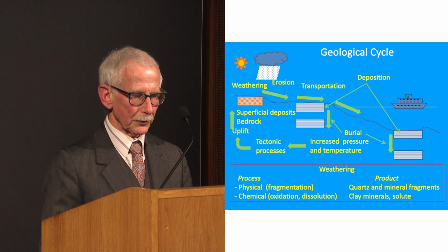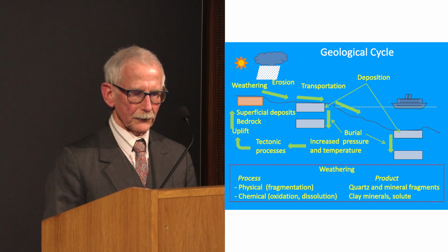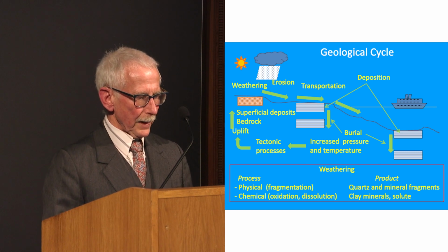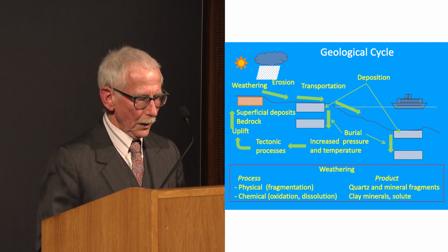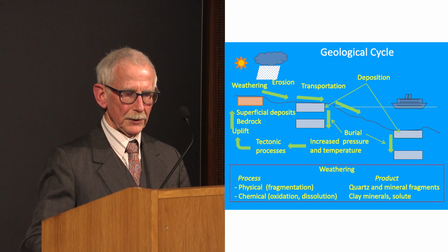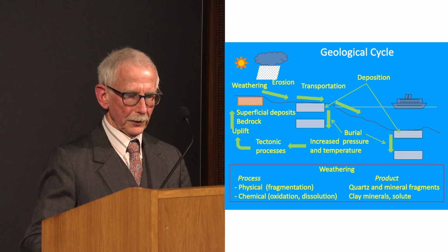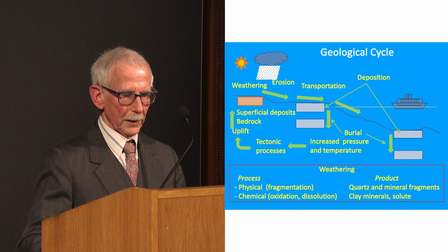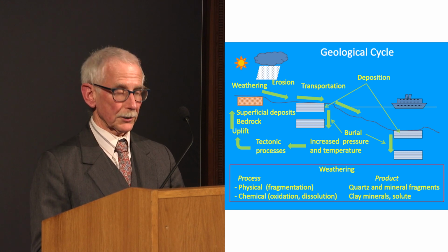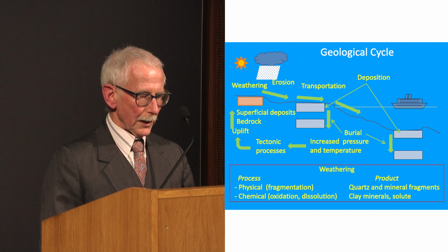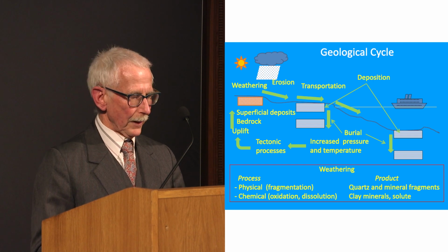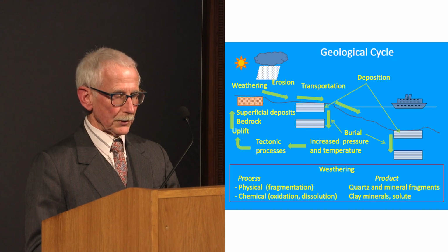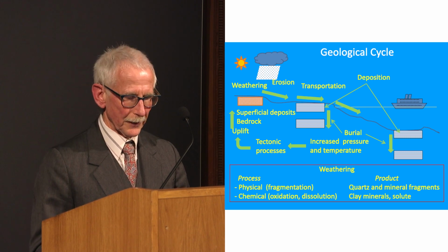But in the case of sedimentary rocks we're talking about, uplift has occurred to form land so that the overlying deposits have been eroded away and eventually they become subject to weathering action. Burial and exhumation of these deposits might be over very long periods of time, hundreds or thousands of millions of years, or it may be over a much shorter time, and it may occur in repeated phases of burial and exhumation. The loading and unloading of ice sheets during the last glacial periods and the effects of periglacial conditions, the freeze-thaw action, may also impact on the properties of these materials, soils and rocks, and the structures that they contain.